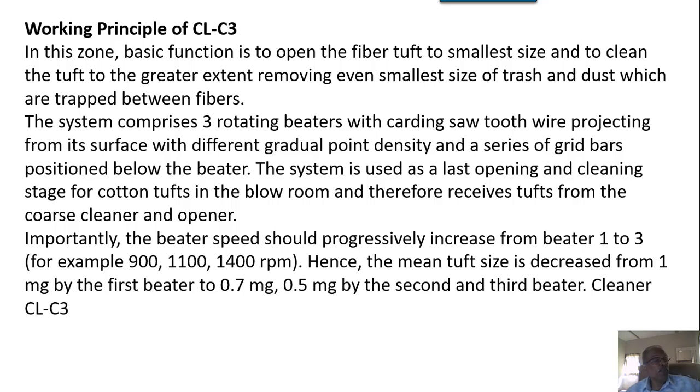If you are consuming foreign cottons, then that situation is a different one. So what I have mentioned here is to clean the smallest size, and to a greater extent, removing smaller sizes of trash and dust which are trapped between the fibers. This is the basic philosophy followed in the beaters.